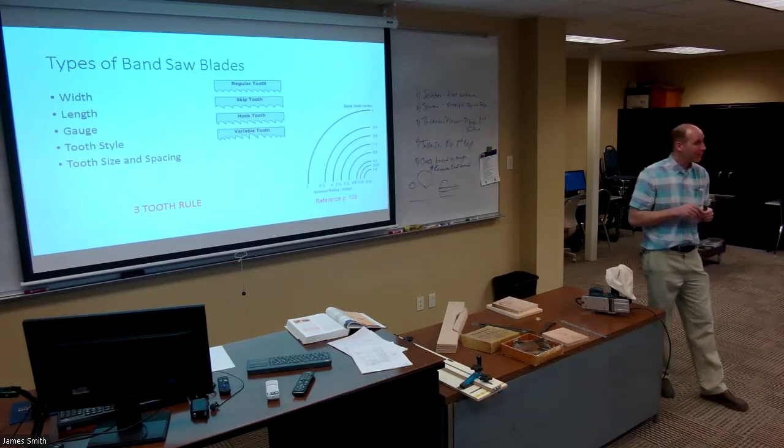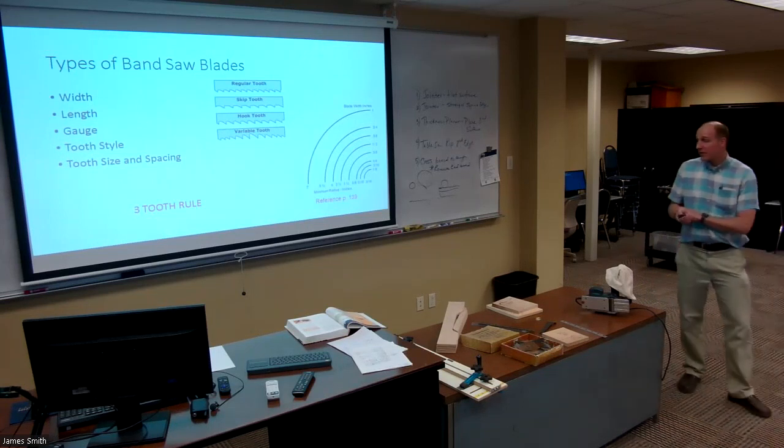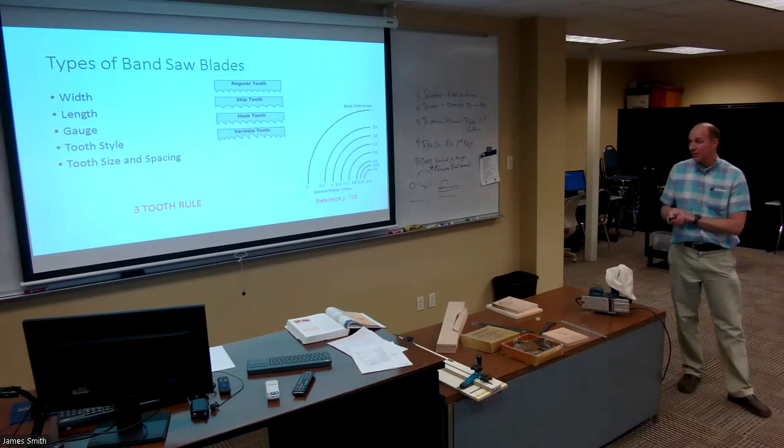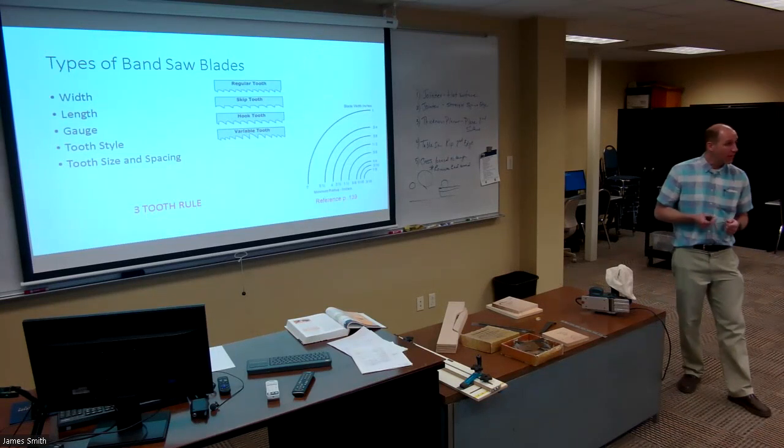We were cutting through that, but stainless steel is so hard. If I was to push that in, it would strip all of my teeth off. Okay, so you had to. That's generally not a good thing to do. But the 3-tooth rule: if you abide by that, then you're not going to need to worry about stripping the teeth off your blade.